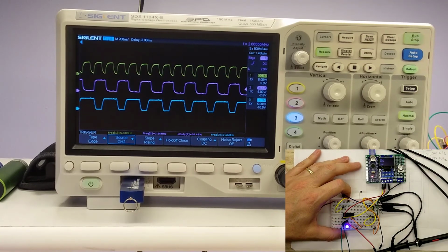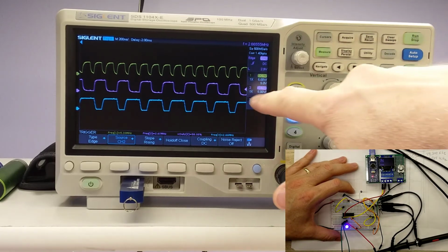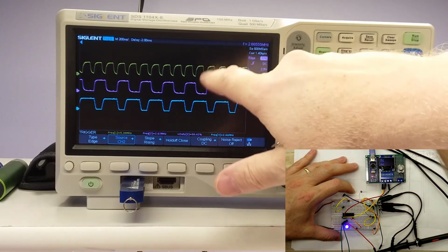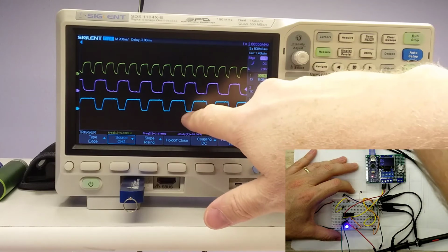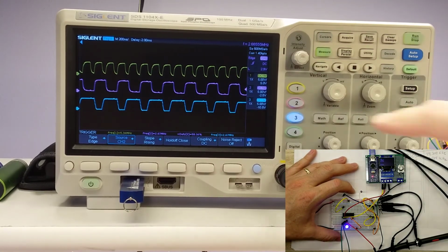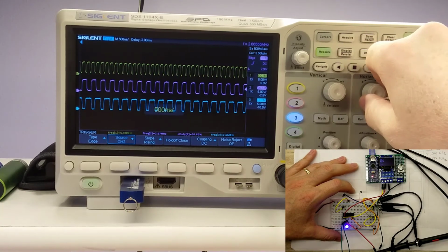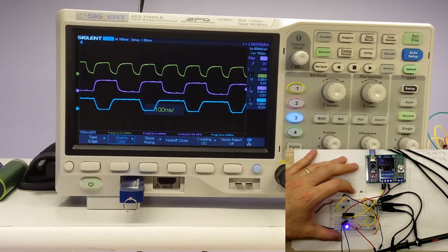Now we have it cranked all the way up to 5.3 megahertz, and as you can see, it's holding up extremely well. So again, when both of them are high, the output will be low. And I'm currently triggering off of the pink one just so that it lines up nicely, and it does work really, really well. So I would say this chip actually outperformed the AND gate from just a pure being able to keep up standpoint. That's a really, really clean output that it has.